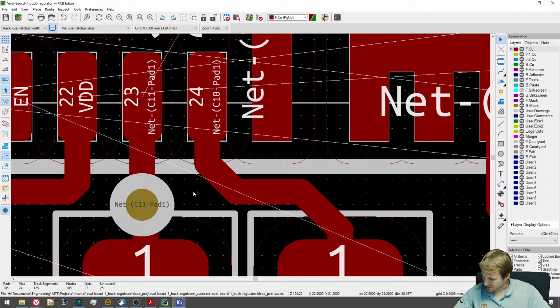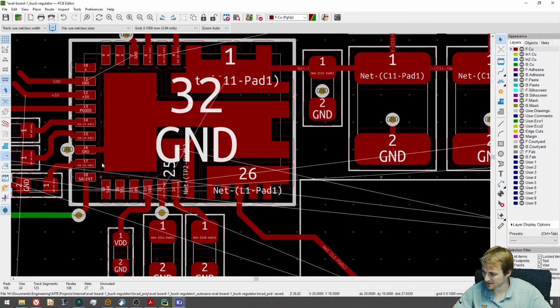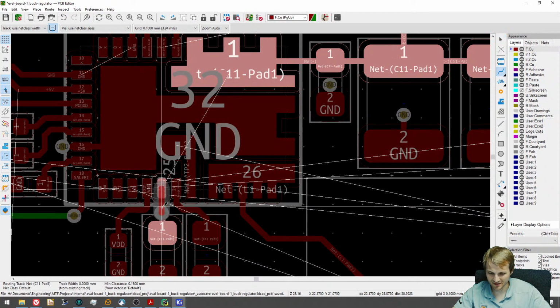From the viewpoint of noise and jitter analysis, voltage signal at two remote sensing pins indicate not only load's terminating voltage VO, but also external interference picked up. That's from the app note. Yeah, I mean that makes sense. I just wish they would have said that in the data sheet.